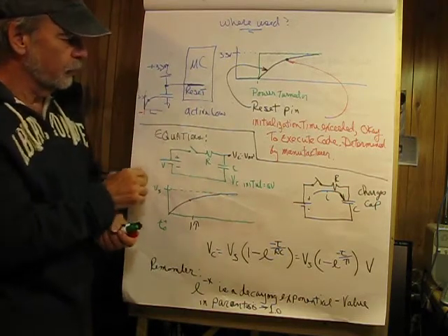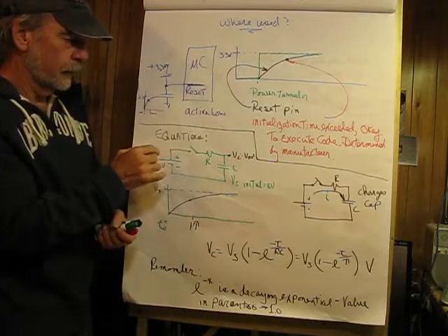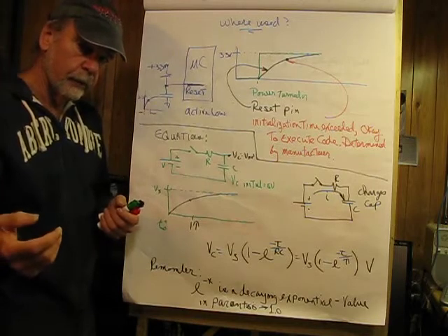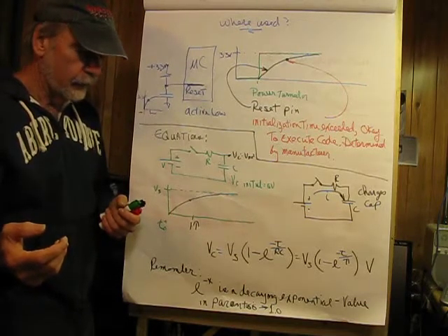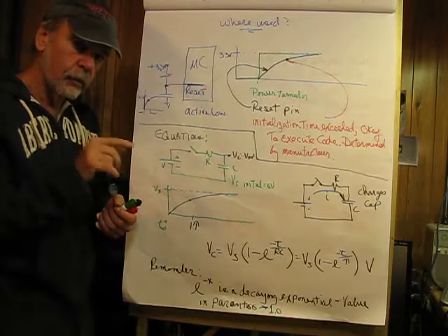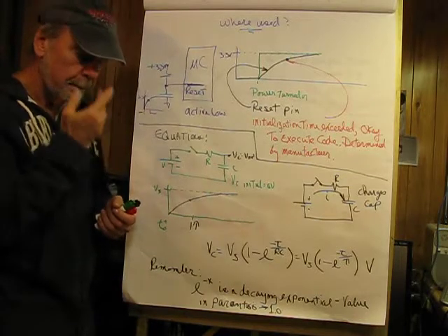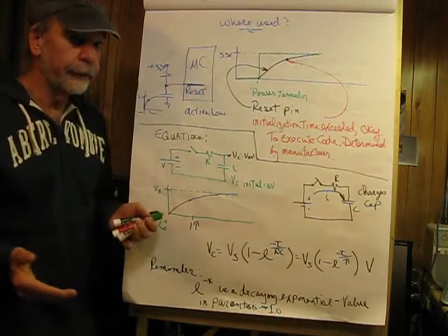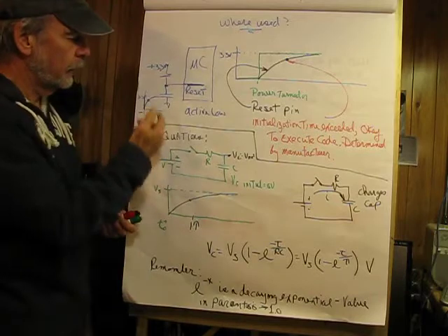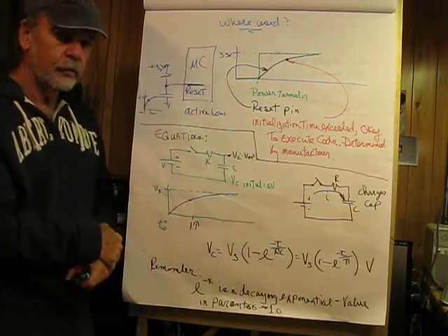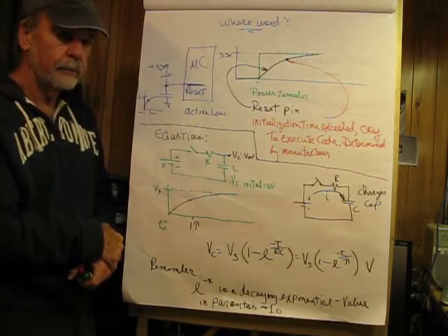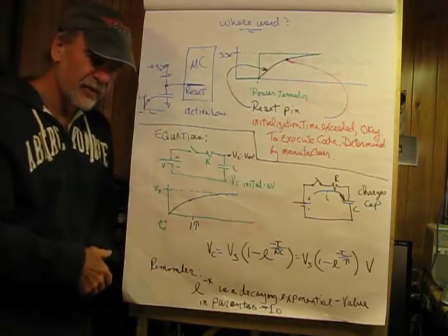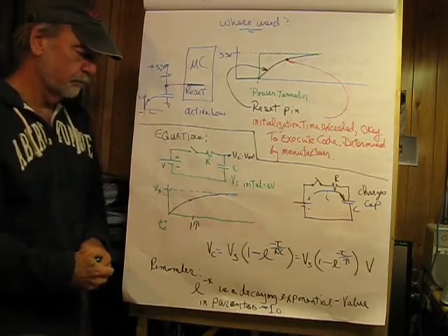I once designed a little display using a controller to drive a laser, pick it up on a photocell and display the result. And I had the laser bit rate very slow so students could see this pulse. And when I fired this up, the controller wouldn't work. Then I read the data sheet and learned that my time constant was way too small. The processor couldn't initialize. Fix that, all is well. I guess the message is it pays to read data sheets.